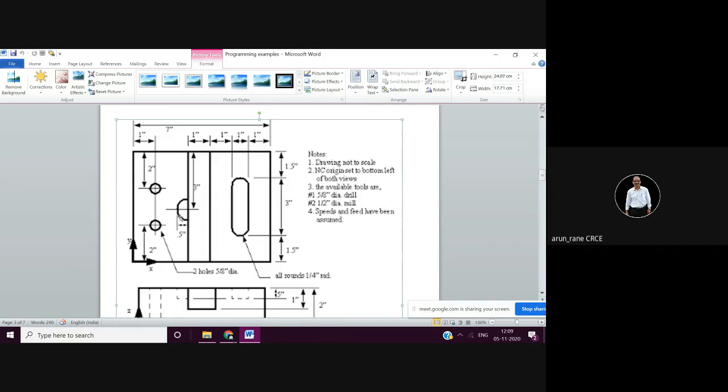So I will get this slot. But now this radius will be such a semicircular, a full half inch radius will come. And X will be 3.5 to 3. So I'll get this. Then I will lift the cutter rapidly, G00 Z 2.2, meaning 0.2 above this. Now I'll bring the cutter to this position. Now you have to calculate this position. What is this position? X will be how much? This is 4, this is 5 or half inch. So 5.5. The cutter's center line comes at 5.5.